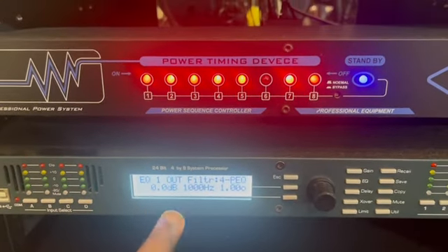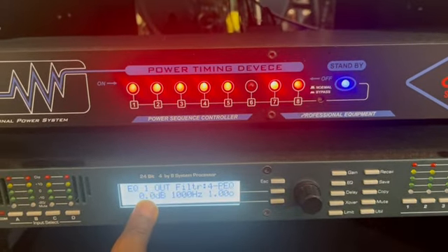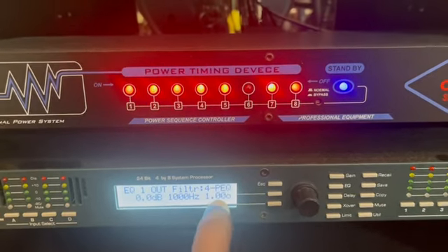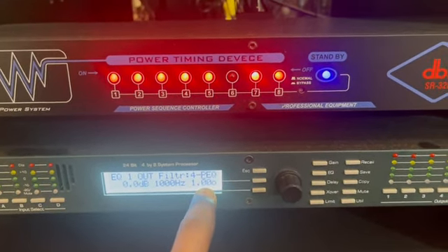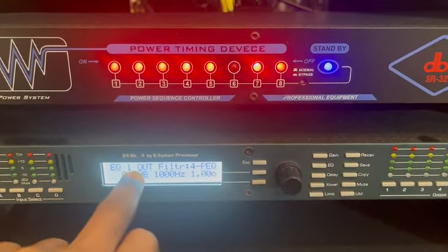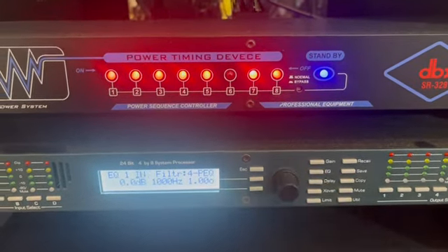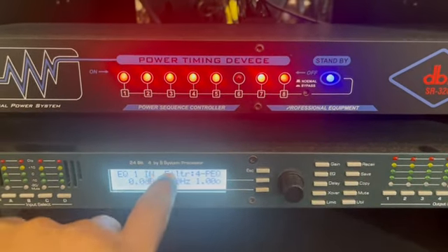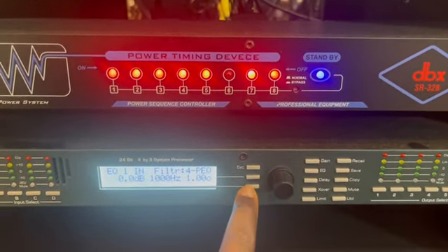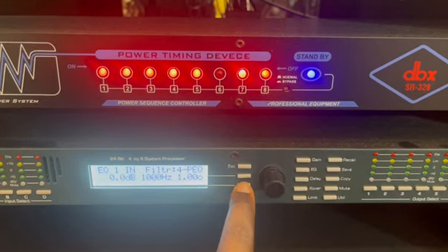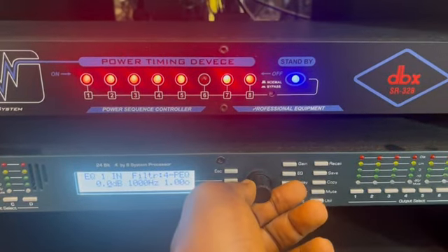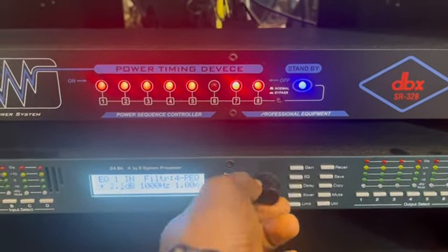Yes, so you see you have the dB, that is your gain. Okay, and this is the frequency, and this is the octave, or the bandwidth, how you want to control the bandwidth. Okay, so let's toggle back here. It's out, EQ1 is out, so I'll turn my jog and it's in, meaning I have activated this parametric EQ1. Okay, so for you to do this, you have to toggle down this button here to cycle to where you want to go. So let's say I want to boost 1000 hertz, that is 1k, 1 dB, I can.